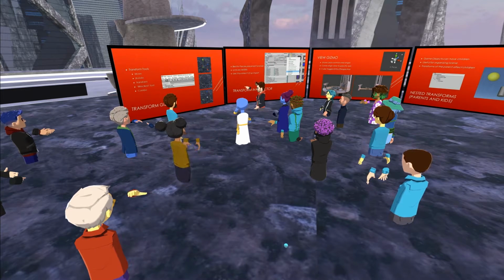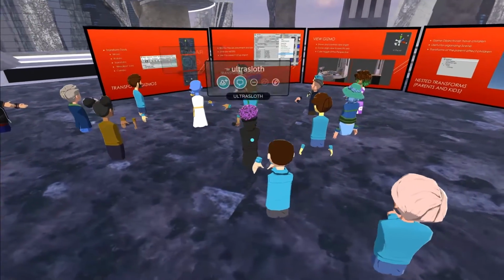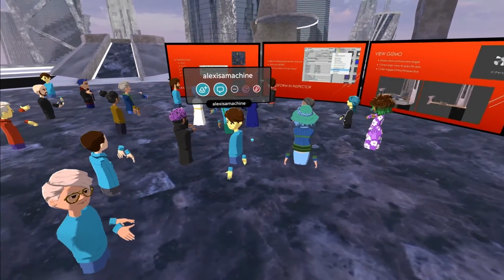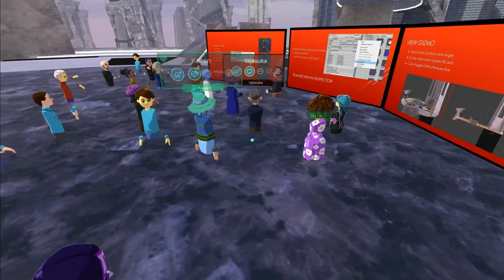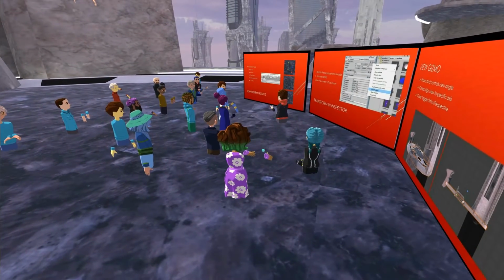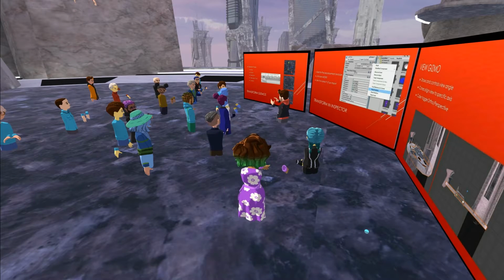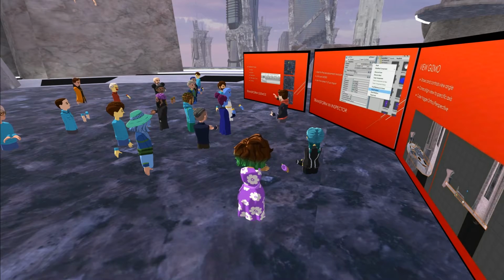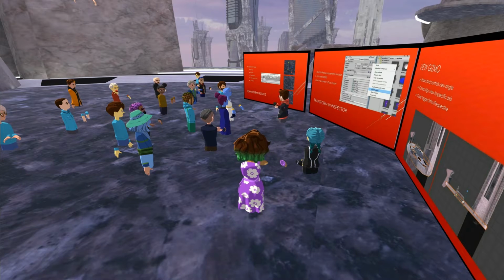The rotate tool works in a very similar fashion. I've got these different colored circles around the sphere, and if I grab one of those and turn it, it will lock that rotation along that plane. It'll only rotate around one axis. If I grab the sphere anywhere else, not on any of those axes, and just start dragging it, now I'm freely rotating it. And it actually rotates in two directions at the same time, depending on what kind of effect you want.